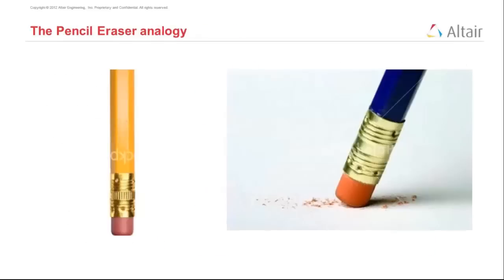In the pencil situation, you want the grip to be lesser so that the rubber slides on the paper. But in the tire situation, you want to maximize the grip so that there is no sliding between the tire and the road. You are not in the dynamic friction region, but you extract maximum possible grip between the tire and the road.